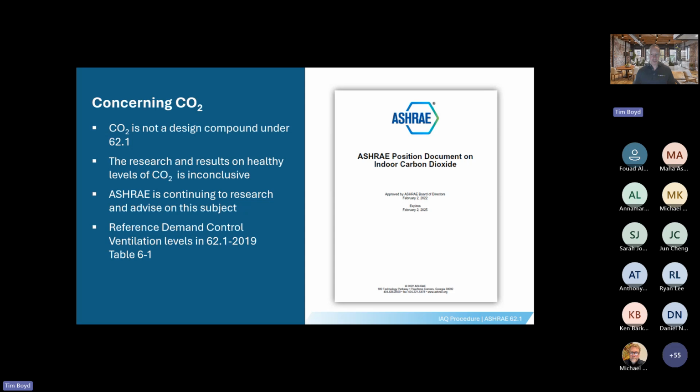And this is even more fundamentally key to understand. When you run through the calculation and you see what the pollutants are, the first ones that are causing you to add more clean air or add more outdoor air, it's almost, I'm going to say 90%, but fundamentally formaldehyde and PM 2.5 are the first ones to pop. They're the first ones to create problems. Basically, building off-gassing and outdoor pollutants, not people. And so this really is foundational to understand. Carbon dioxide historically has been used as a proxy or as something to kind of determine air quality. ASHRAE has debunked that and said it is not a good indicator of air quality.